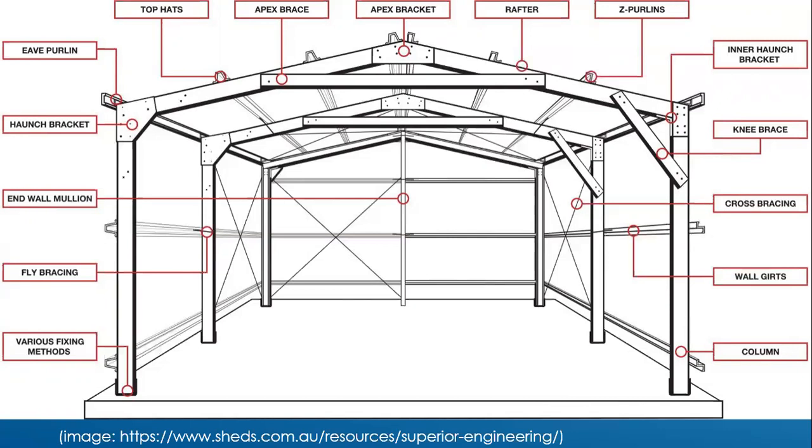Columns and rafters are usually braced by collar ties and knee braces, with purlins and girts providing stability. The portal frames evolved from historical arch construction, as was used for cathedrals and bridges for centuries. The benefit of portal framed construction is that the self-supporting construction is capable of large internal voids, providing maximum usable space.